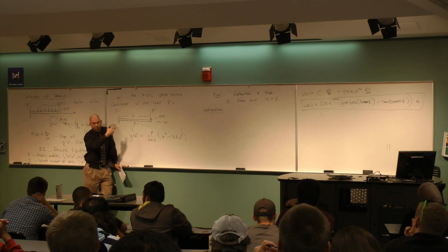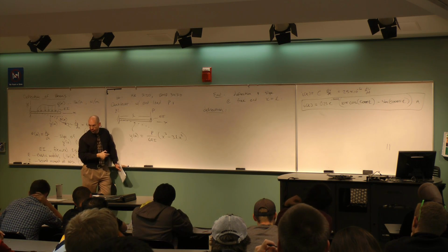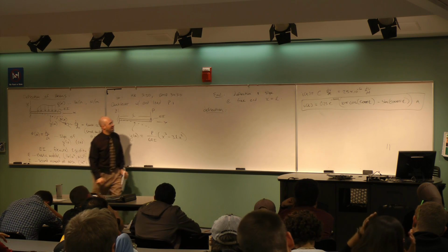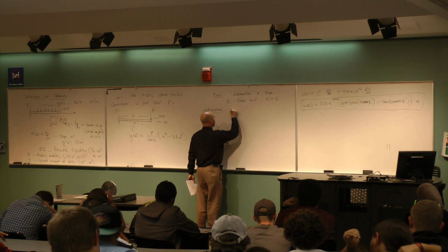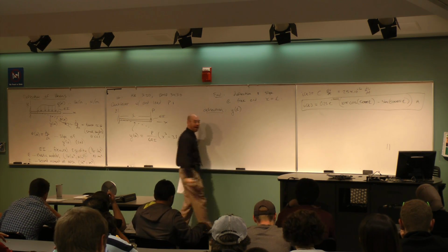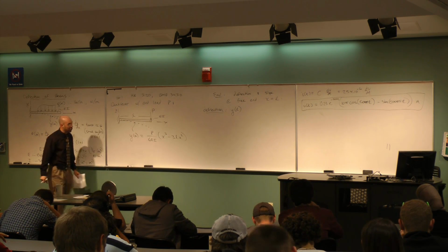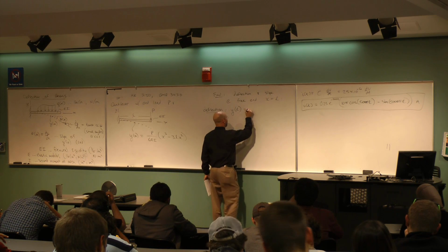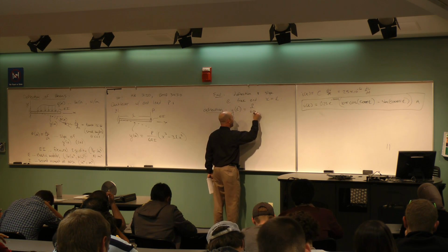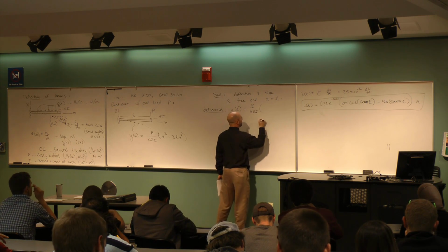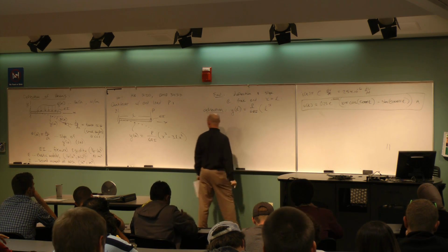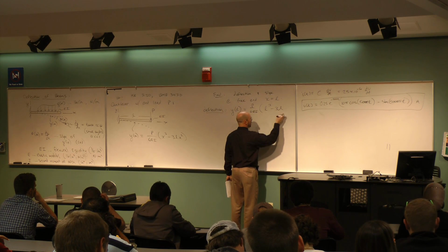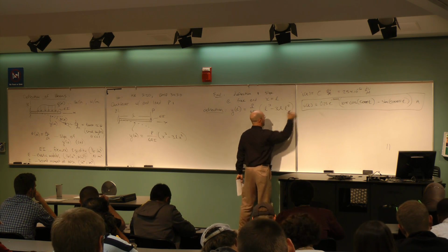Okay, so the first physical question we're going to answer, there's no calculus here. This is a piece of algebra. Let's plug in the L and see what we get. For the deflection, I need y evaluated at L, not multiplied by L. Plug in an L for the x. So I still have P over 6EI out front, and I've got x cubed, so that's going to be L cubed minus 3L times, I plug in an L for the x, L squared.